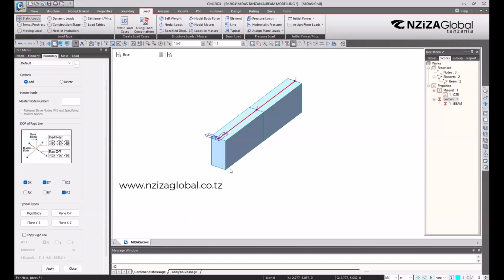Okay. Then later, they may put in the girders. If it's a T-beam, for example, they will be cast monolithically. But after 14 days or 28 days, that concrete will no longer be wet. It will be drying. So all those weights can be inserted there, so that we analyze things which are real in the construction stages. Is that clear? Or am I not hitting the point?